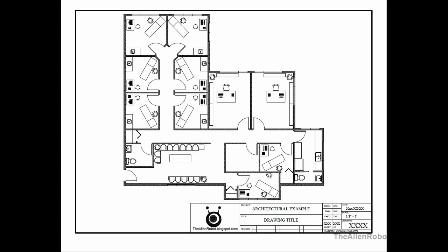On my screen is an example of the finished block. Imagine you have saved a drawing on your network drive that contains all the title blocks and layouts you'll need, and anytime that you need those title blocks and layouts, you can easily drag and drop them into your drawing. Layouts give you the power of automating your title block insertion.